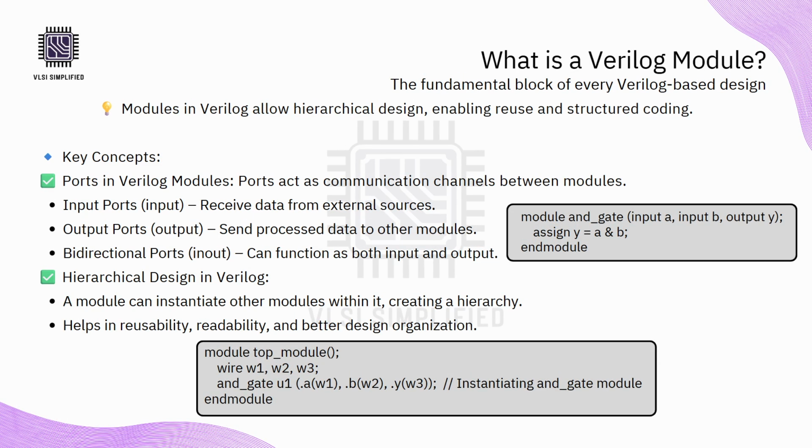Let's take a deeper look into what a Verilog module really is. A module is much more than just a block of code. It's a design unit that encapsulates a specific piece of functionality. Think of it like a hardware component with well-defined inputs and outputs. It is the smallest unit of hierarchy in Verilog, and it allows us to build large systems by breaking them down into smaller and reusable parts.